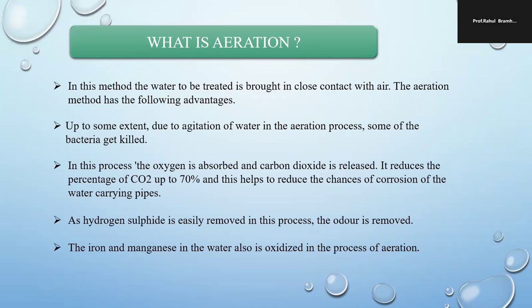To remove the carbon dioxide from the water, absorb the oxygen, and remove the various odors from that water. So these are the purposes of aeration.